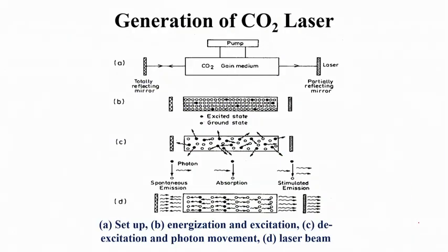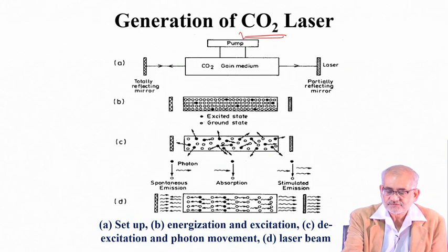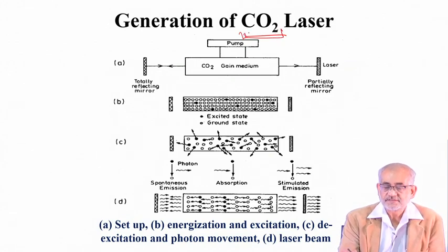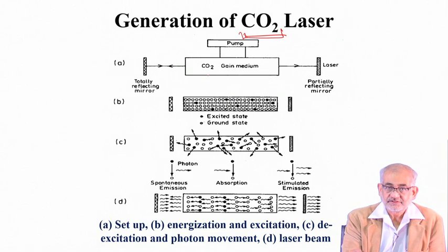So just a minute on the generation of laser. In this case, we are talking about CO2 laser. This was one of the foremost types of high power laser that was useful for material processing. So essentially you have a medium filled with various carrier gases, and a part of that, the active species of that will be CO2 of very low volume fraction though.